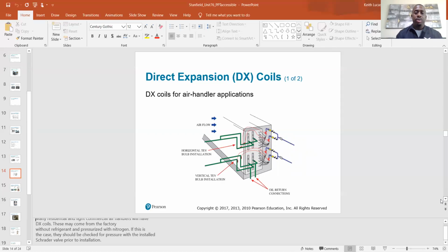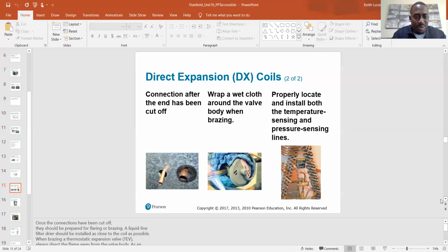Last thing you want to do is install the entire unit and then get all the way to the point of doing your evacuation, and then your evacuation never coming down, and then moving into leak checking to figure that out, and then find out that your coil has a leak in it. Well, actually, you wouldn't even get that far. Once you braze the system, you're going to pressure test it, and at that point, once you see that your joints are solid, but you're still losing pressure, then you're just going to feel cheated because your coil is leaking and ruining all your hard work.